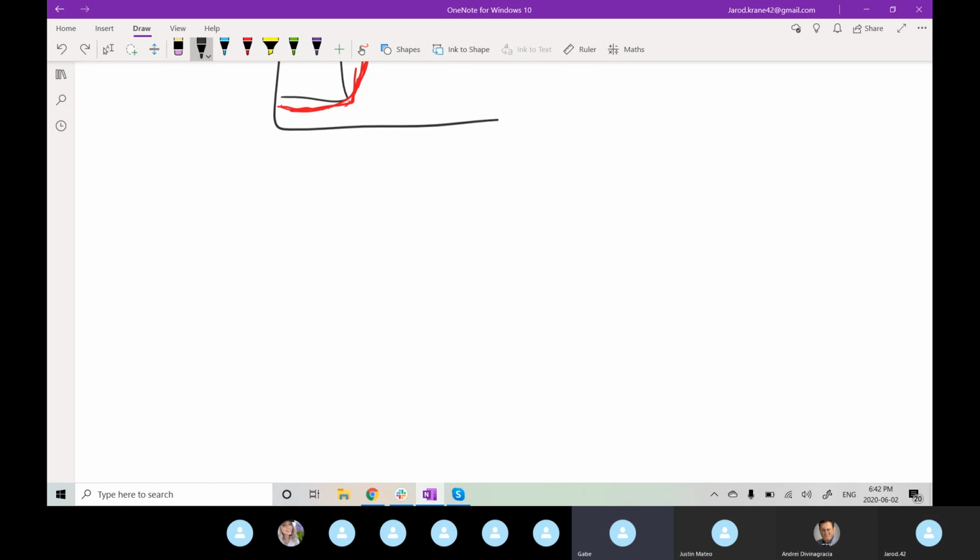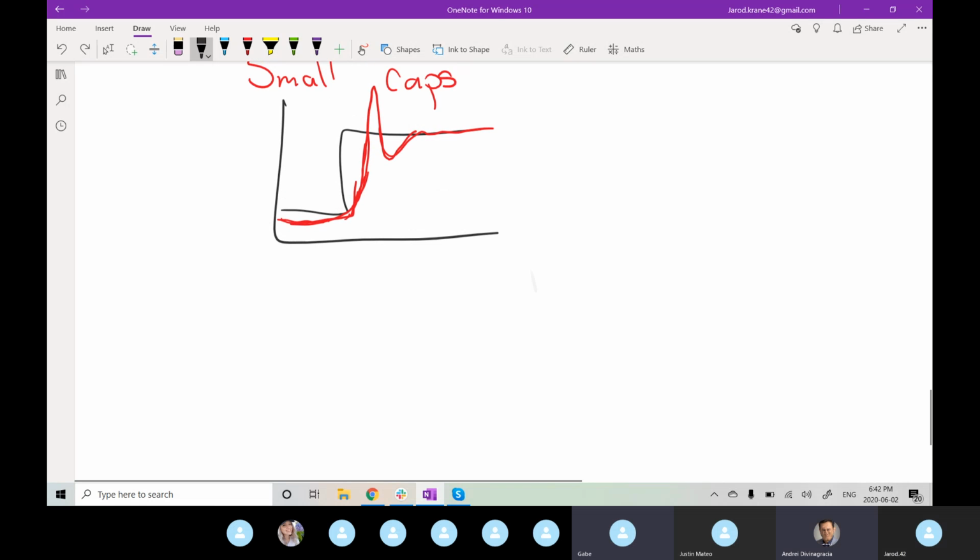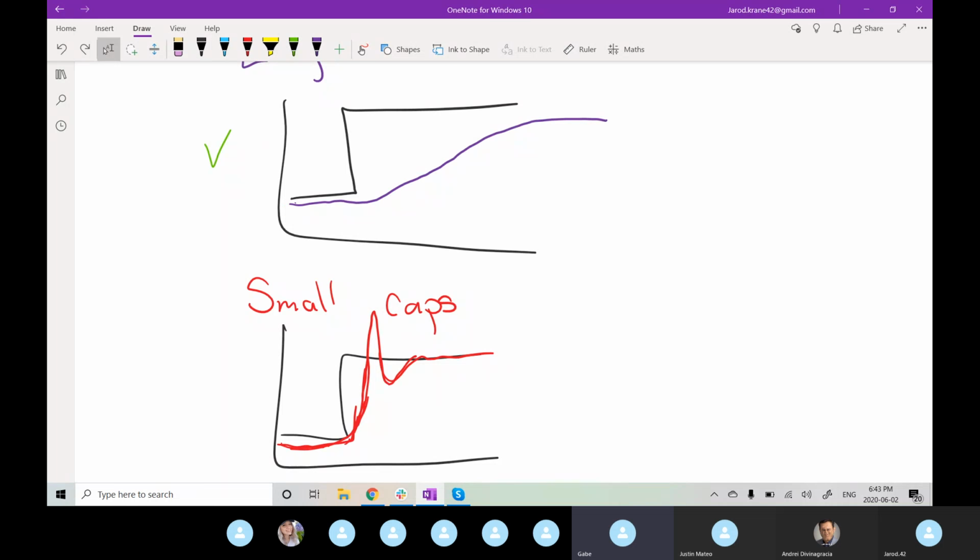Oh, I have a comment. Oftentimes, if you have a large load on your linear regulators, like you're drawing a lot of current from them, the voltage tends to drop. So having external capacitance, even more than the datasheet, can help prop up that voltage and keep it solid.